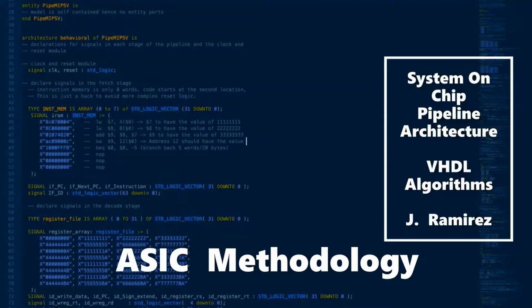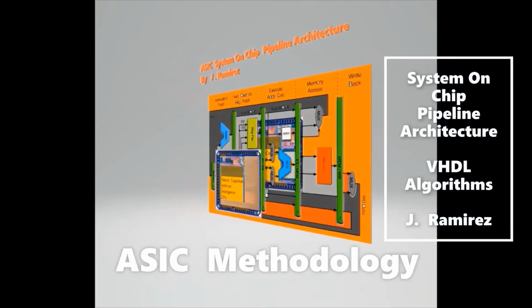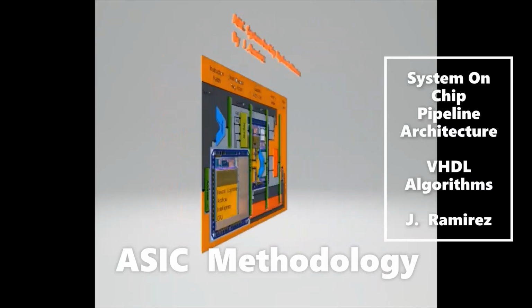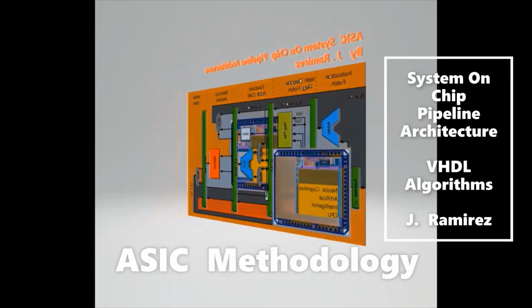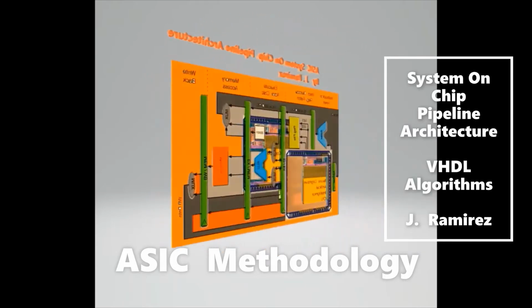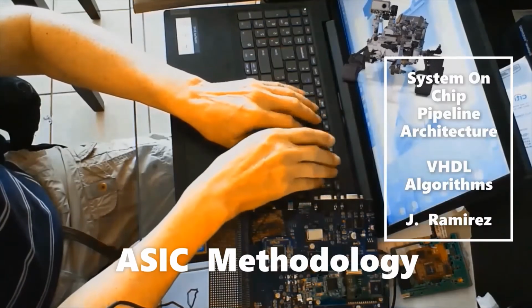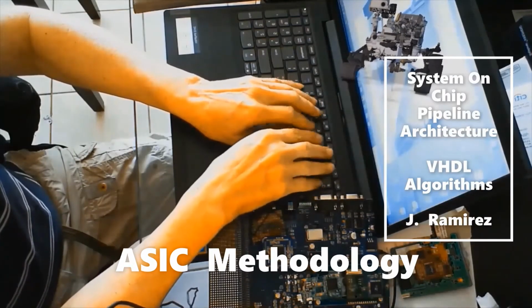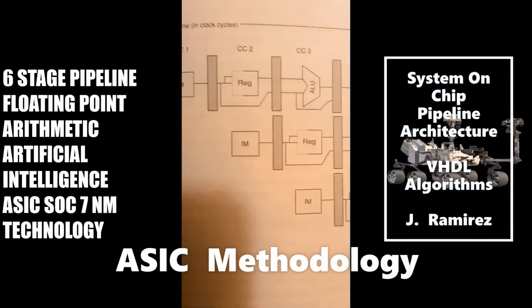The memory stage takes the output of the arithmetic logic unit and puts it into the proper memory location if the instruction is a store. The memory stage contains the data memory object. It connects the data memory to the register bank through the write back stage to read and also to forward on information about the current write back register.